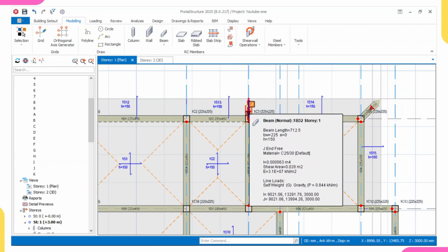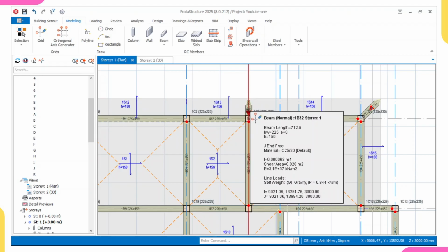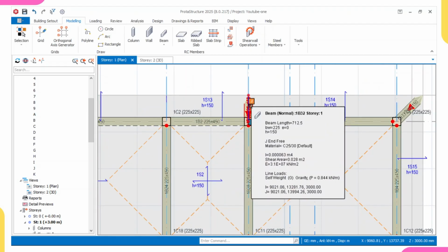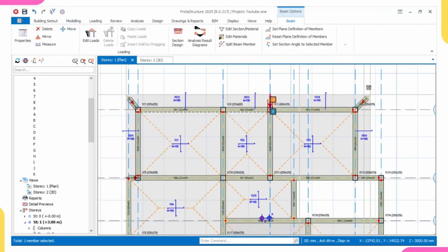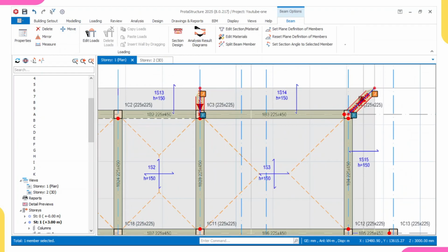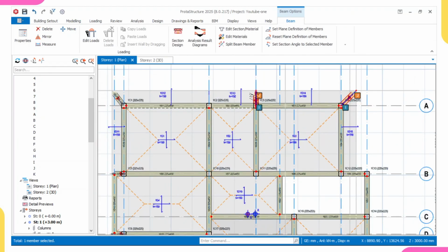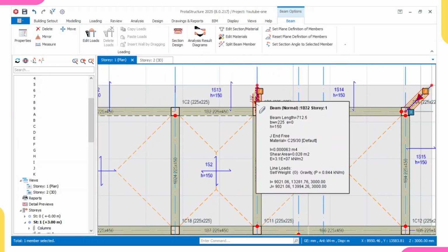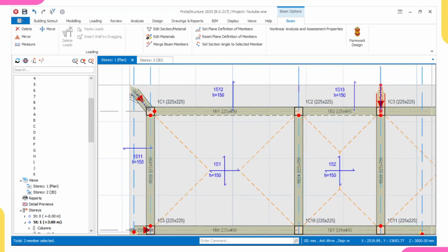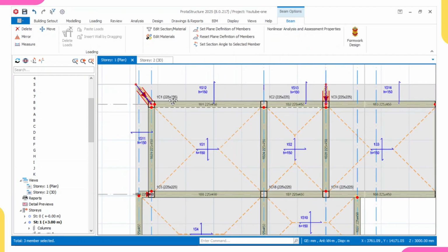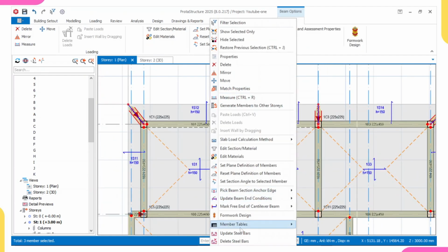If you don't hinge it, you'll see that this beam will fail, because the moment on it will be high. So I like to hinge it, because I know in real life I will not really input this beam. In construction I'll just provide it as a hidden beam. But I want to hinge it because I know it will sustain. I don't know if you understand what I'm explaining, but I just want to hinge it.